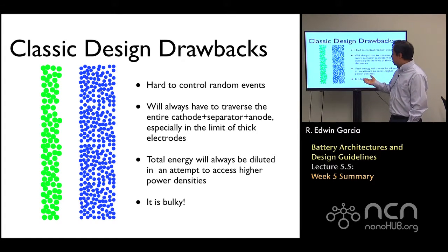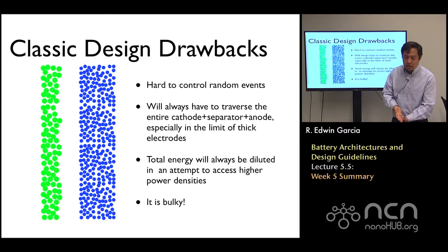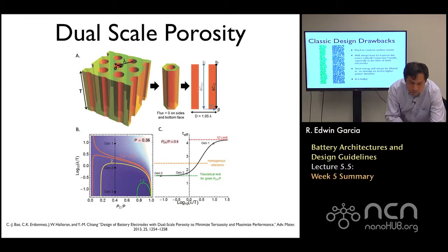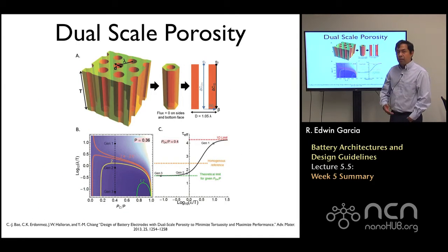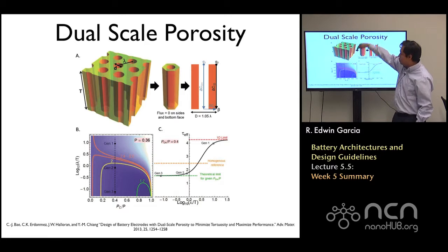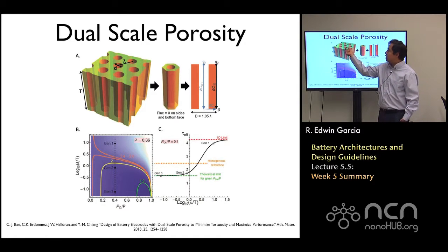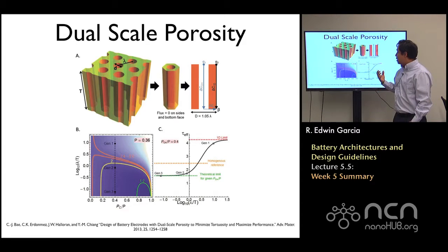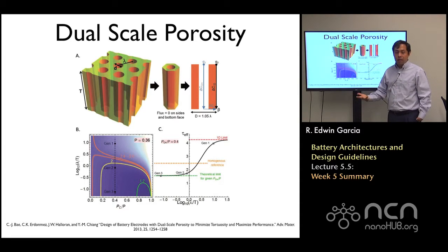So what people have done, and they have gone below the classic window where batteries are used, which is somewhere between 30 to 60% porosity, and instead they have tried to go below the 20%, sometimes 10% or lower, and they bring back high transport limitations by performing tricks such as adding this additional linear porosity in the system, which allows you to basically engineer the spacing between pores, the size of the pore itself, and therefore increase the capacity of the cell.